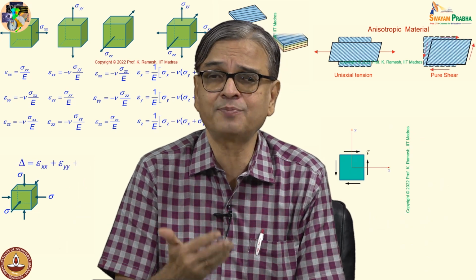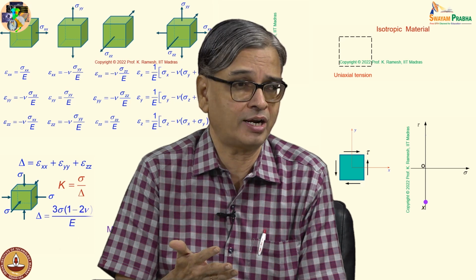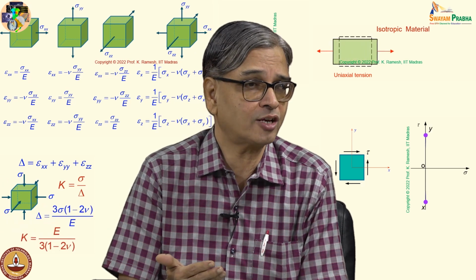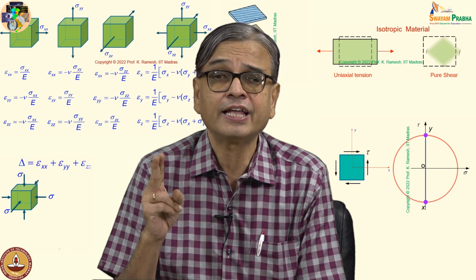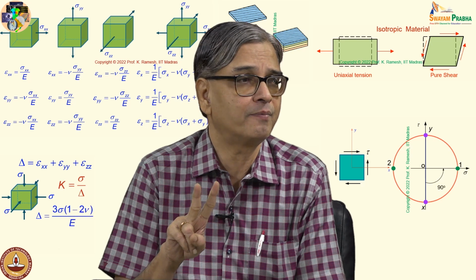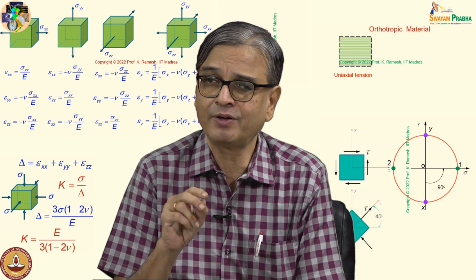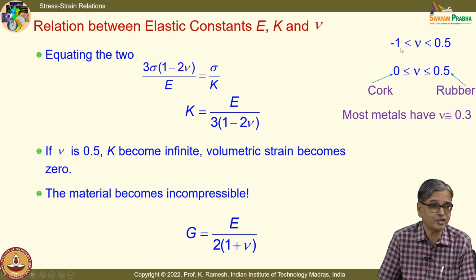You may give Young's modulus and Poisson ratio, or bulk modulus and shear modulus. You can find out all other quantities. An isotropic material requires only any two of the 4 elastic constants that we have brought into focus. And we have also seen what is the limiting value of the Poisson ratio.